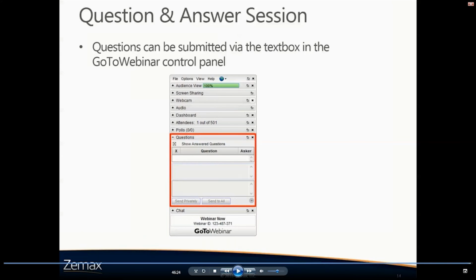For example, the BSDF scatter type will actually ask you for a BSDF profile to use in reflection and a different or same BSDF profile to use in transmission. That's because with some of the measured scatter behavior, you could actually see differing behavior in reflection versus transmission. So we allow application of different scatter profiles in those two instances.